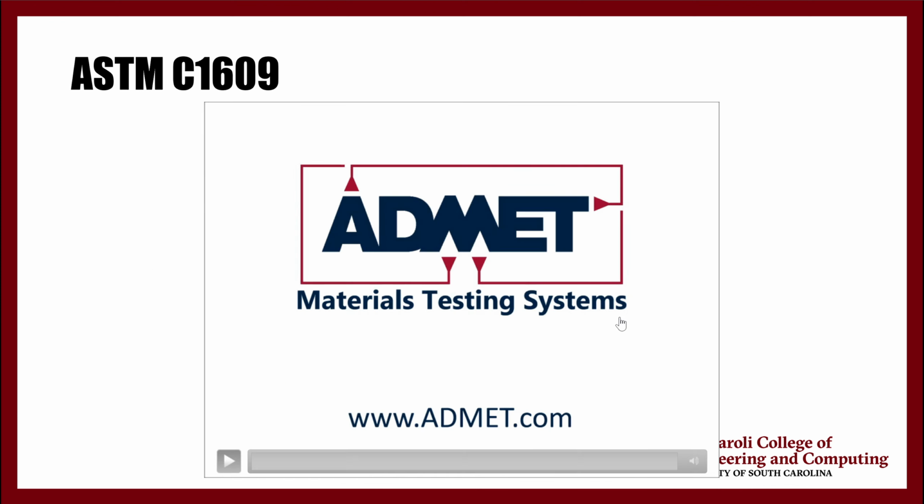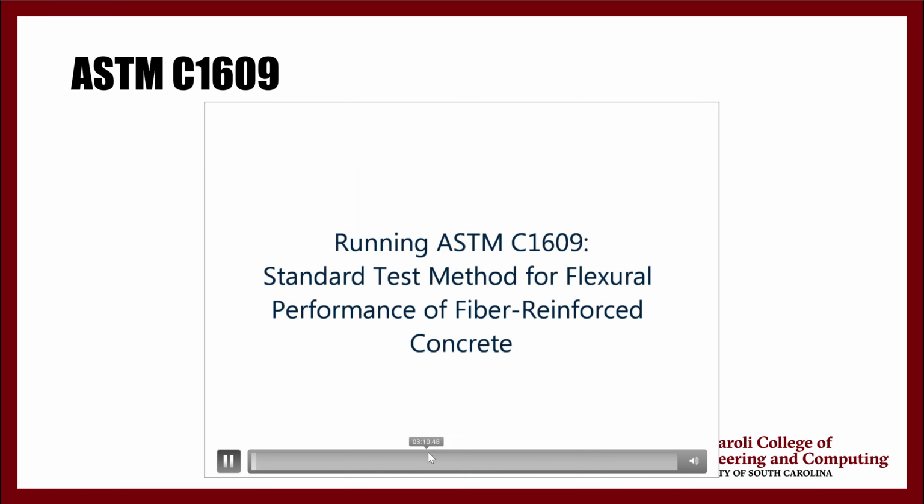Okay, let's see an example of a 3-point bending test that is done based on the ASTM standards that are available for concrete testing. So this is ASTM C1609, which is the standard test method for flexural performance of fiber reinforced concrete. Whenever you want to do any sort of test to measure the flexural performance of a fiber reinforced concrete, you have to do the test like this.